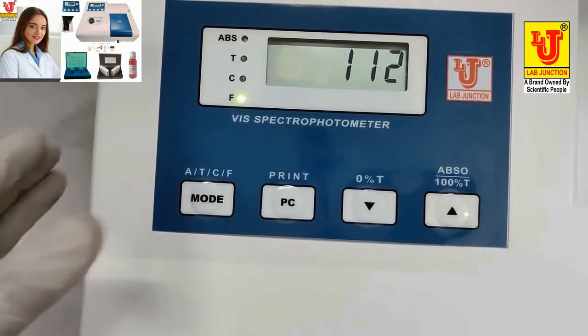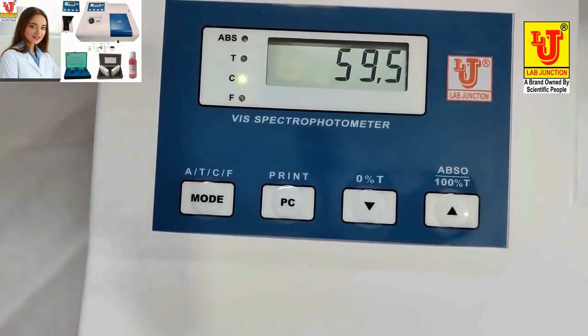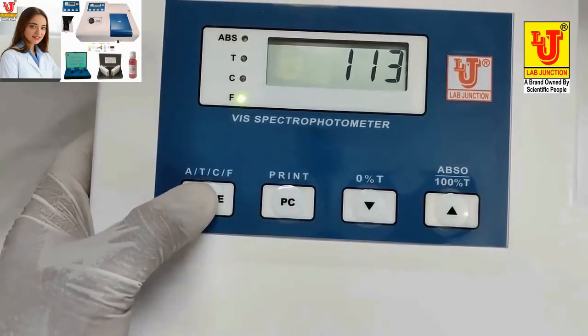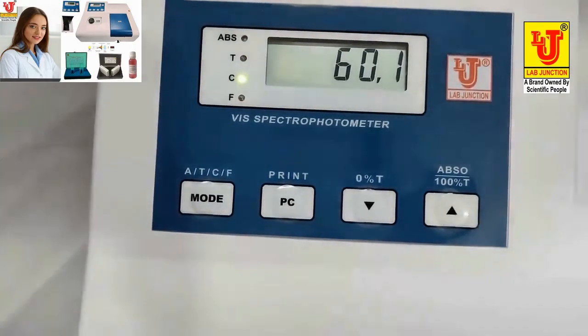112. Now go to concentration mode. It directly shows the concentration value 59.5. Again go to factor mode. If I am feeding 113, it directly shows 60.1. Now the spectrophotometer is calibrated in concentration mode. Now you can insert unknown samples in the sample compartment and directly take your results in concentration mode.